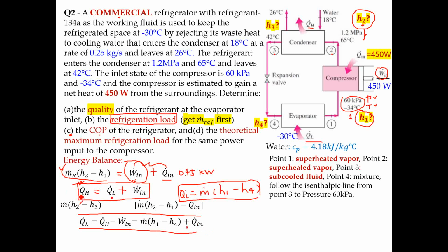So this is from the derivation of equations, but physically you could understand it in a way that when we have this refrigeration cycle, the compressor is working and generates some amount of heat, and this amount of heat also needs to be removed by this cycle. So in that way, when you are considering refrigeration load, it contains not only the amount of heat you need to remove from the environment, but also the heat generated by the compressor as well.